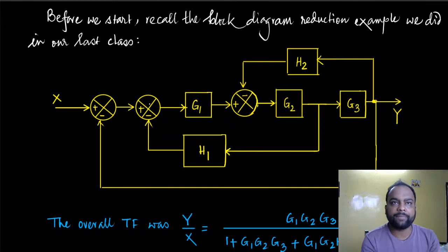Instead, it tells you that if you remove a certain branch from here to there, then you have to do some computation like this. If you combine two blocks like this, then you have to provide certain computation like that. Then this is the equivalent block. So block diagram reduction technique gave you the equivalent blocks for some primitive block configurations.